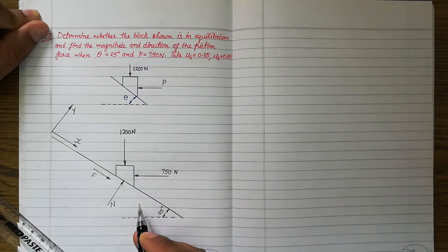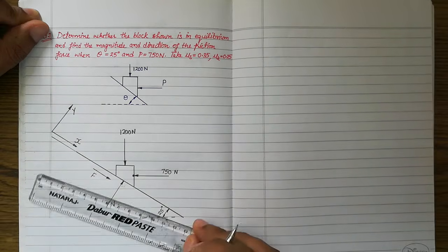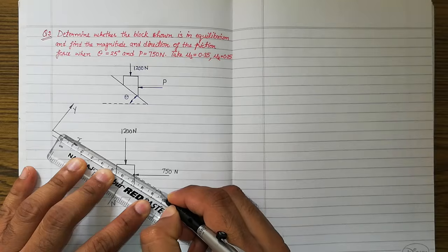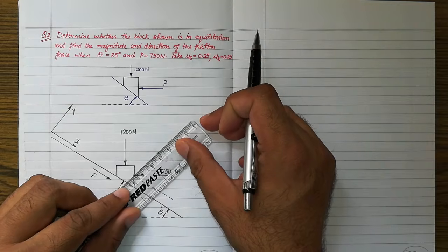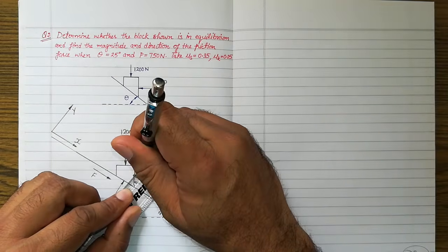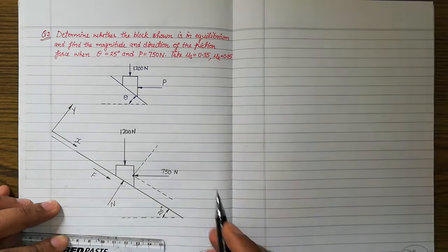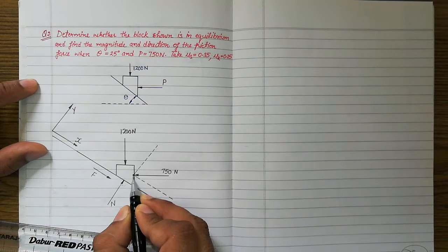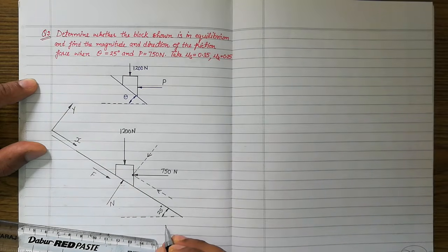It means the next step in the free body diagram is that we should label the components of this particular force. So how to label? Now this is the point of application of this particular force. From that point we will draw two dashed lines. One will be along the x-axis, that is along the surface. From that point of application we will show the second component normal to the inclined surface, or along the y-axis. Now you see the arrowhead for this particular force is pointing towards the point of application. So in these two components also the arrowhead will point towards the point of application.